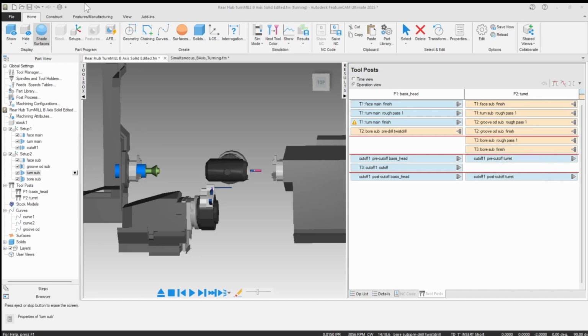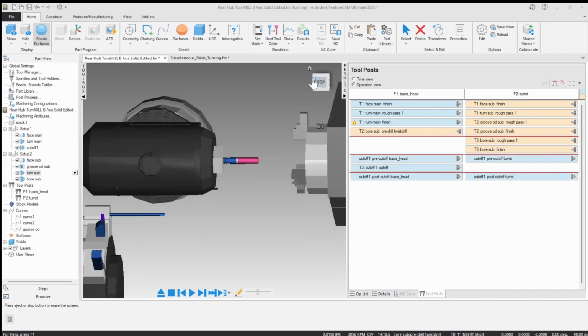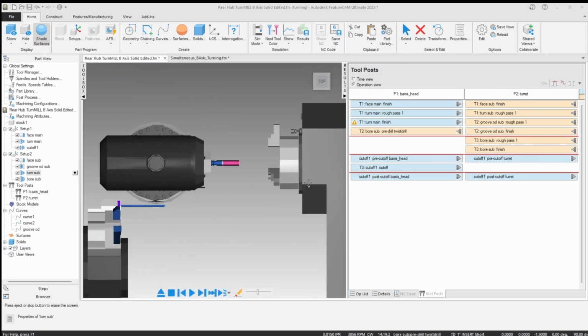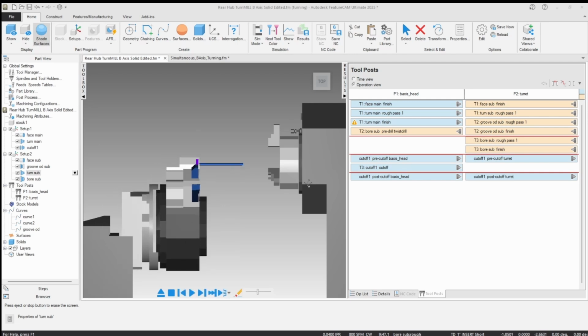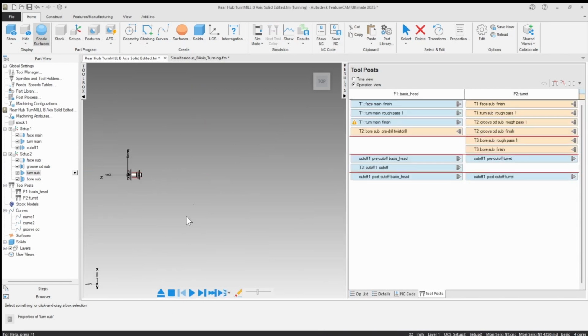So this is drill, looks like an end mill. That's actually an inserted drill, or yeah, inserted drill. So that's why it's got the flat bottom, because my part has that. So you see it's just kind of previewing through here because I haven't done the transfer and all that stuff yet, right? Okay, so but you see the motion. All right, so let's watch this in full machine simulation.